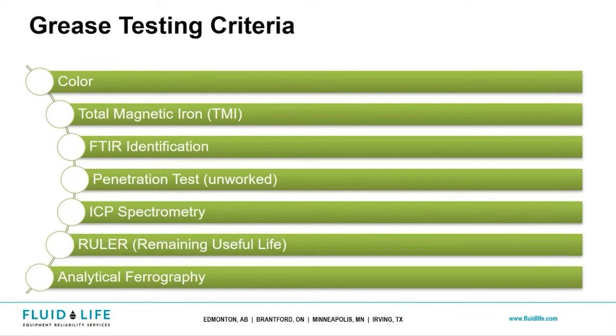This is also really good to give you a step in troubleshooting failure a little bit with things like analytical ferrography. We also have further advanced testing that you can capitalize upon, or we have testing that you can do less of if you're planning on doing things more routinely as well, right? But here you're looking at confirmation of grease quality, grease stability, and grease compatibility to a degree.